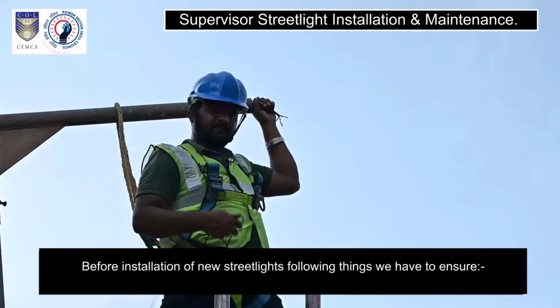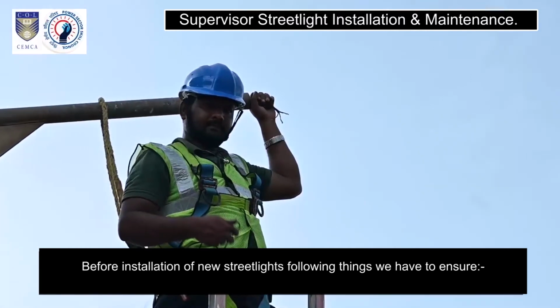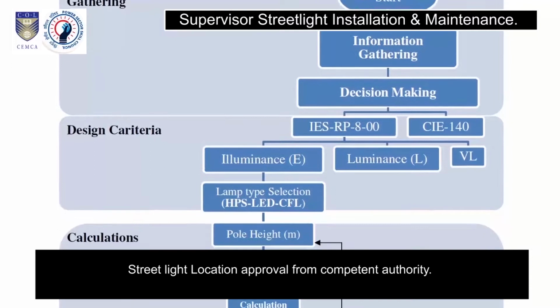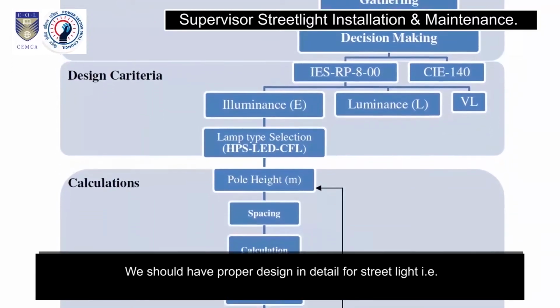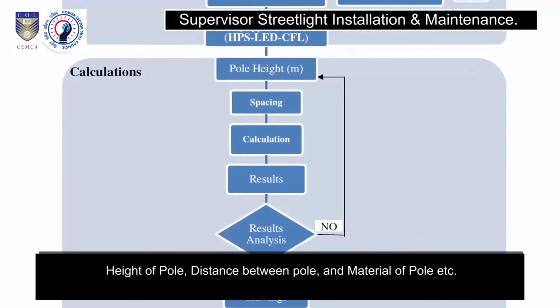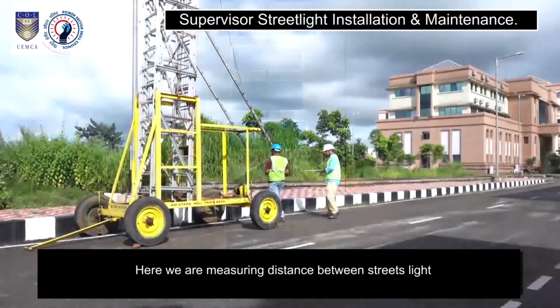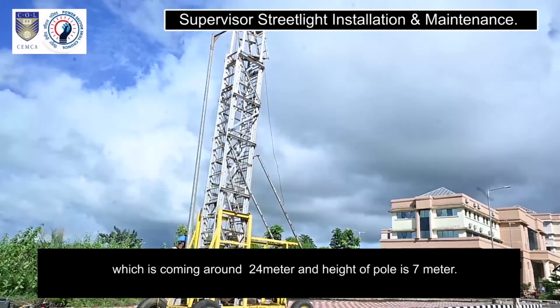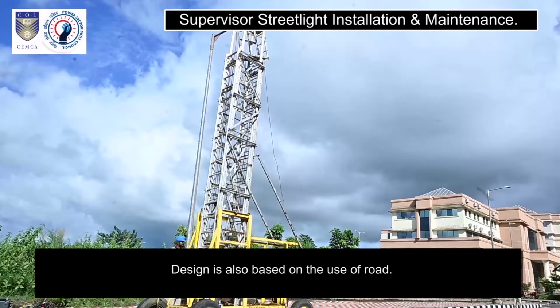Before installation of new streetlights, the following things we have to ensure: streetlight location approval from competent authority. We should have proper design and detail for streetlight, that is height of pole, distance between poles, and material of pole, etc. Here we are measuring distance between street lights, which is coming around 24 meter, and height of pole is 7 meter. Design is also based on the use of road.